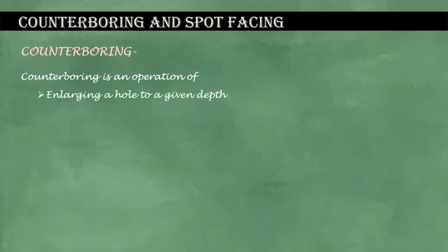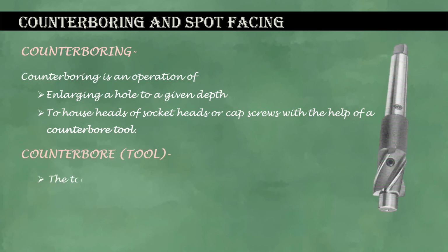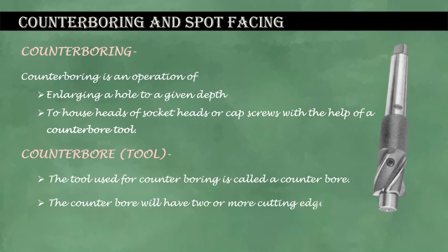Counter boring. Counter boring is an operation of enlarging a hole to a given depth to house heads of socket heads or cap screws with the help of a counterbore tool. The tool used for counter boring is called a counterbore. The counterbore will have 2 or more cutting edges.